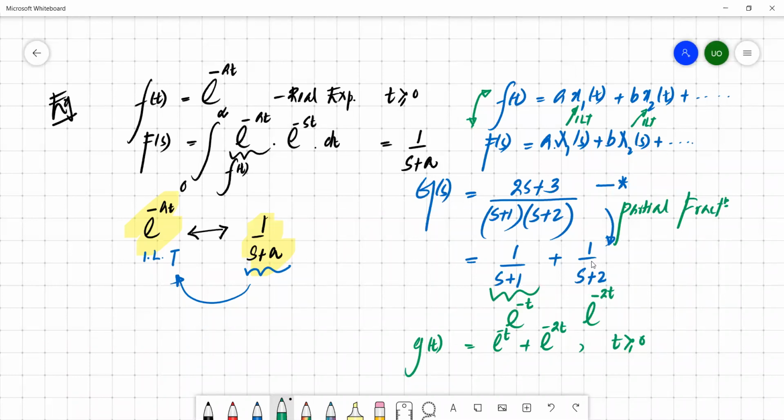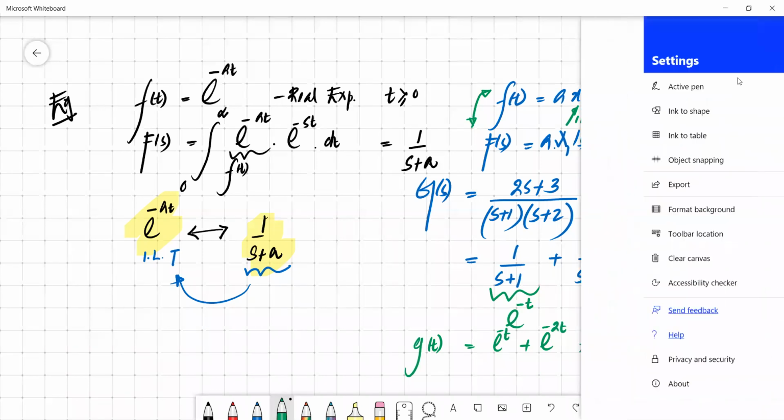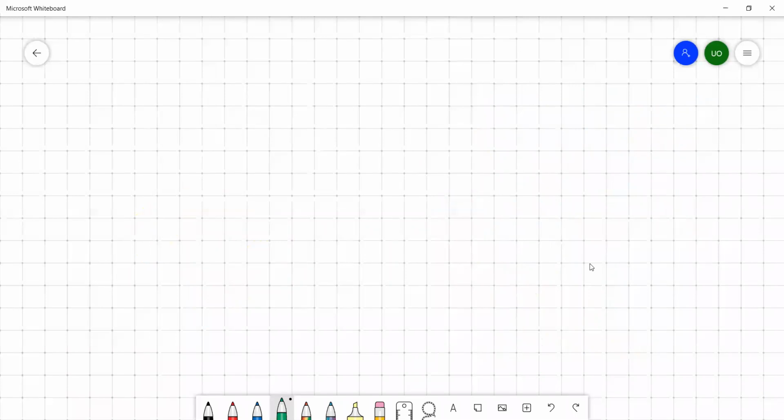What we do here is convert these time domain quantities to S domain by applying Laplace transform, and then if we really need to do a calculation, we can do the calculation in Laplace domain or S domain, and then bring the solution we reached back into time domain by applying inverse Laplace transform. This is the entire objective of having this.